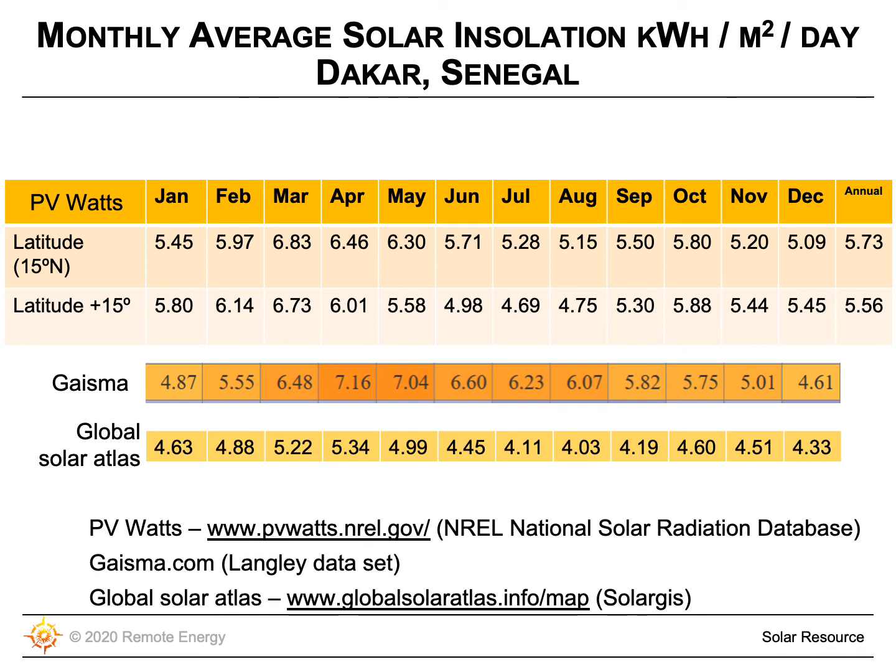And what is that telling us? Well, that probably means that the sun is at a lower angle in the month of January. And therefore, by tilting up the collector to 30 degrees instead of 15 degrees, we're allowing the sun's rays to hit the collector at a more direct angle, closer to a right angle, and we're actually receiving more solar insolation on that surface.